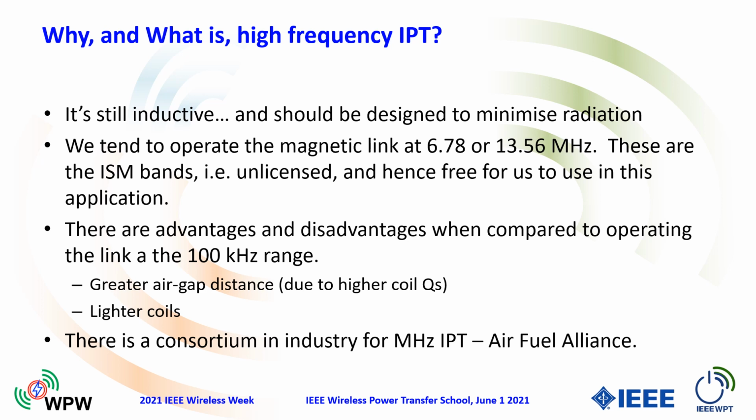And that's simply because as you go to high frequency, you don't tend to use ferrite material in the systems. You don't need to, and I'll explain why that is in a couple of slides' time. So ultimately, lightweight and large distance, those are the reasons that drive us to high frequency rather than sticking at 100 kilohertz.